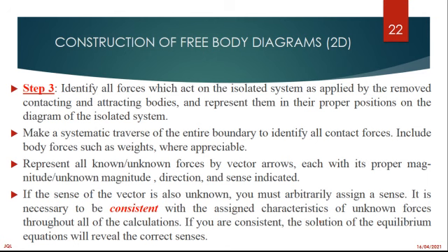Those contact faces are very important for you to come out with what type of reactions you have there. Is it a roller? Is it a pin connection? Is it a fixed connection? And if it's a fixed connection, what type of reaction do I have? Of course, they have a moment and I have a force in the X, a force in the Y. That is in 2 dimensions.